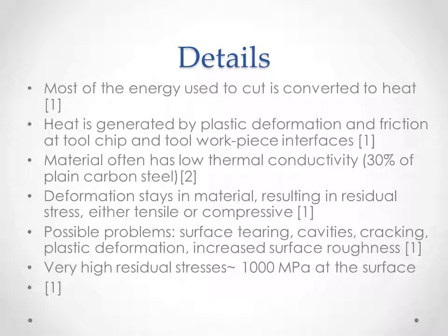There have been some instances measuring after they cut with particular tools, and especially titanium seems to have this problem, and we end up with very high residual stresses, even upwards of 1,000 megapascals.